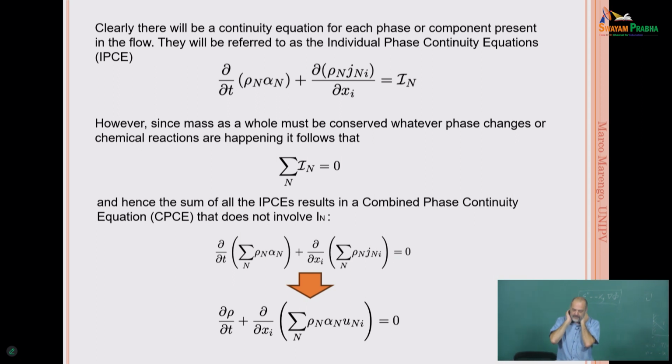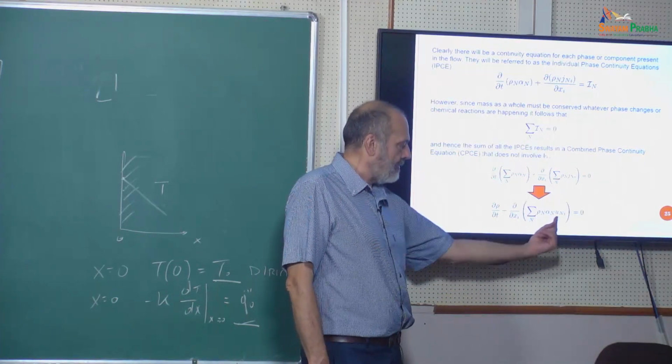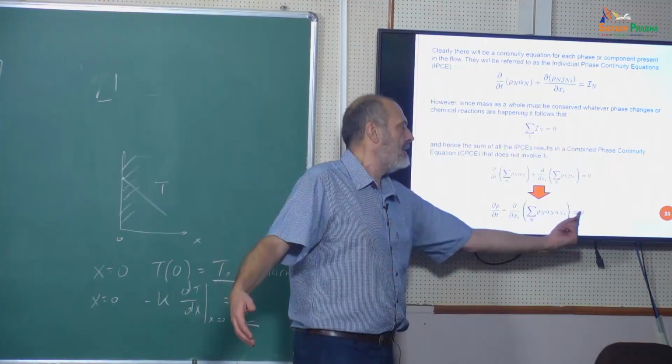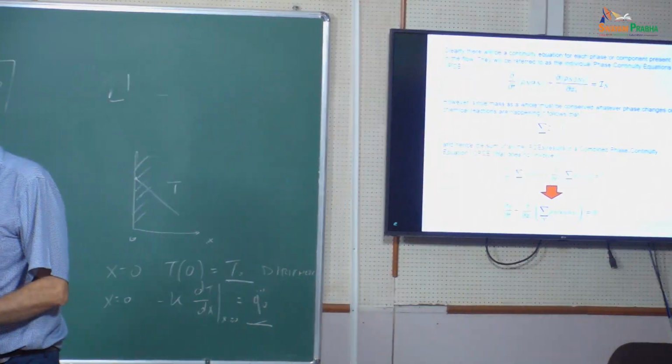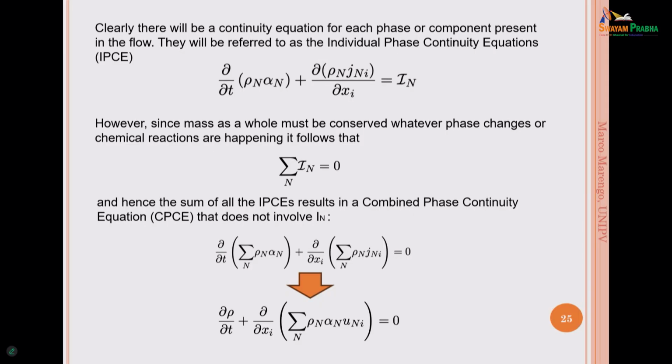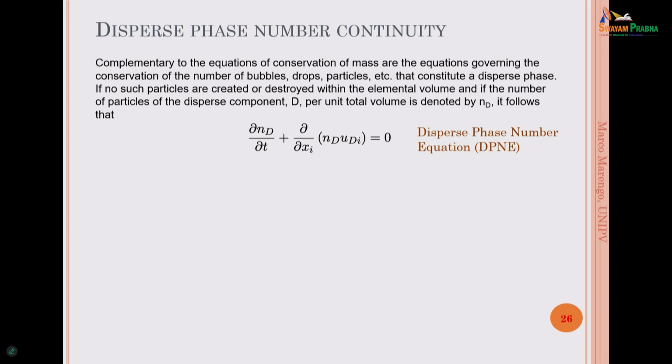Okay. So this means that if we are summing up everything, we are landing with the final equation where, in fact, we have the variation of the density inside the system equal to the gradient of the mass flow rates, considering the volume fraction, and here we have a symmetry. So we have all the components, and here now we have a zero, because we sum all over the components. Okay, so already you can see that we can even consider, let's say, average values.